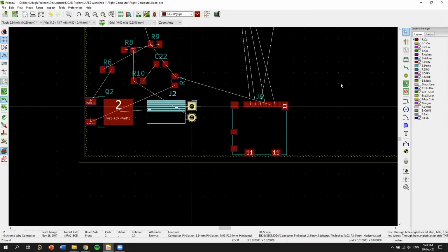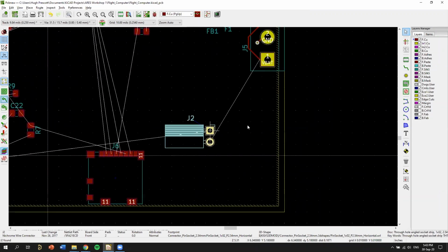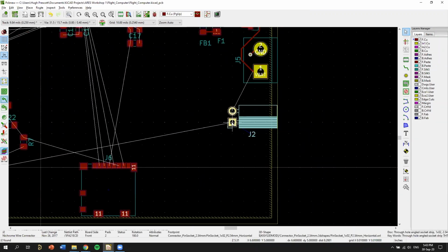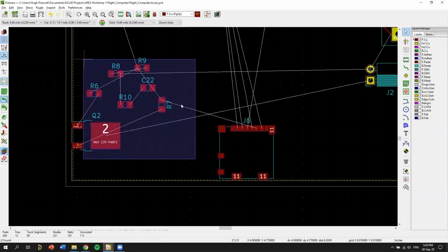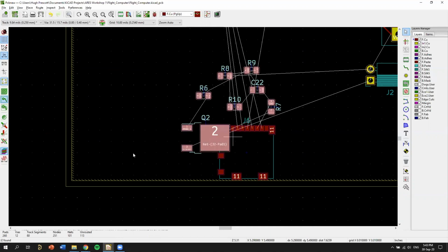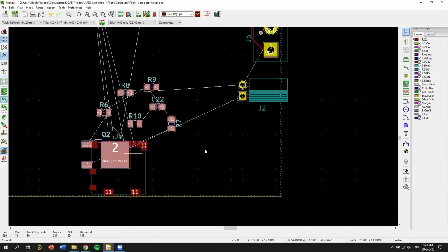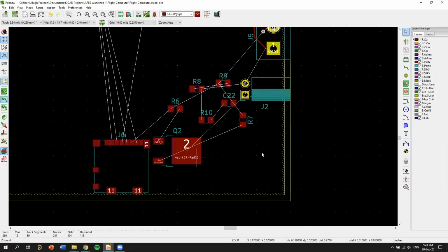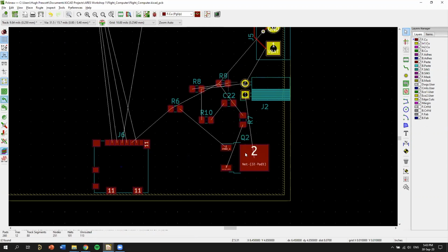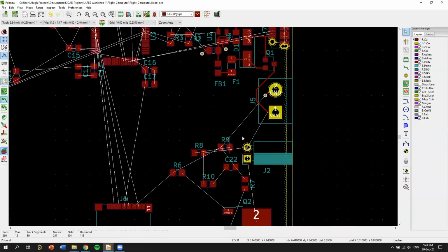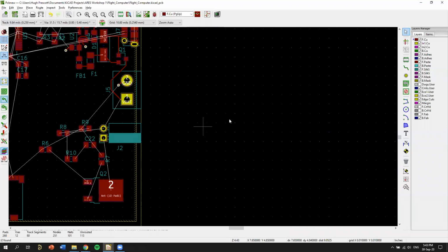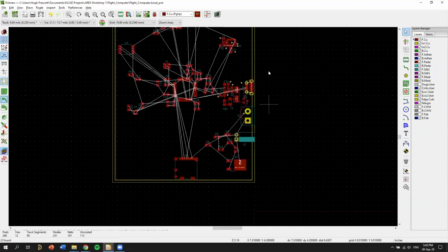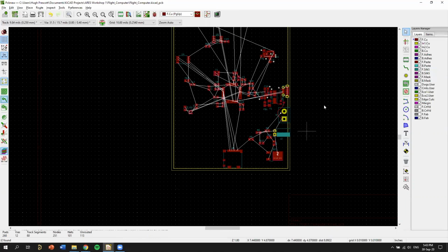Cool. This connector here is for the pyro channels. So obviously the pyros are going to be pulling straight from the battery. Let's chuck that there. I'll chuck all these components on this side. This is kind of what happens as you start routing everything: you realize that there are better spots for all of your components. Because we can just pull our battery voltage or battery current right here and then burn a nichrome wire, an e-match or something. And then when this is mounted in the rocket, that can be where we actuate things.